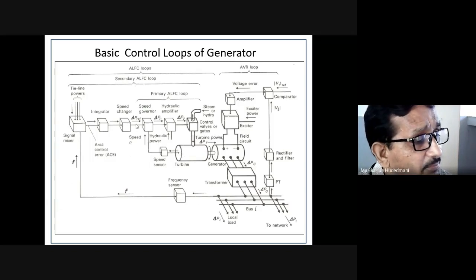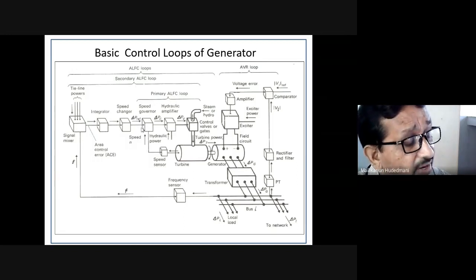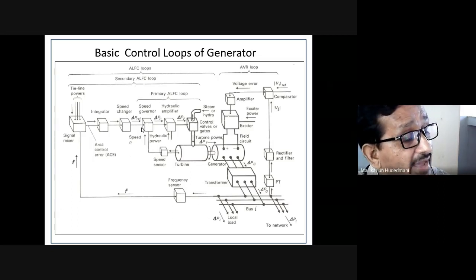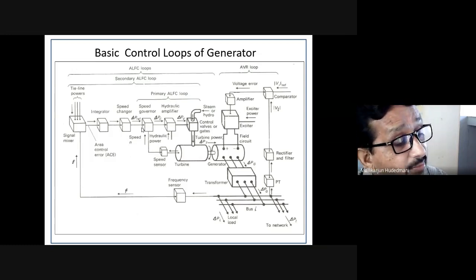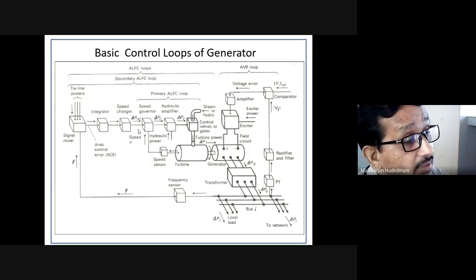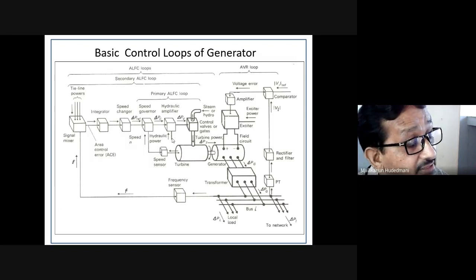For this, some set point will be there. That set point and the actual RPM are mixed and an error is developed. So the governor in this representation works on a prescribed reference point, the set point. In an automotive governor, for example, there could be speed locking, say 60 km per hour. If you press the pedal fully, the maximum speed you can get is, say, 60 km per hour. That 60 km per hour is called the limit set, the reference point.